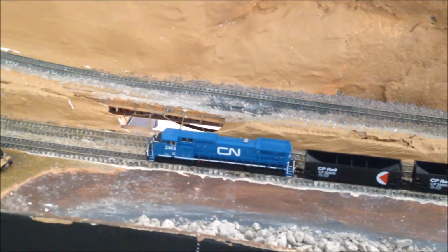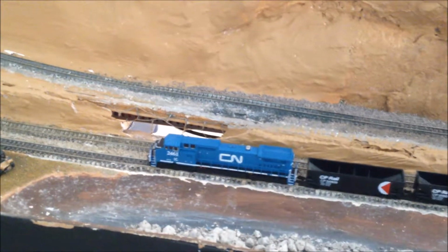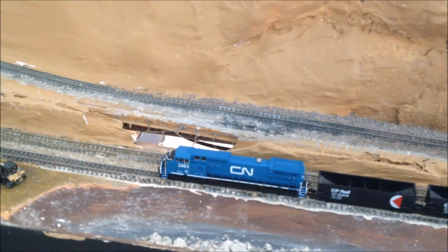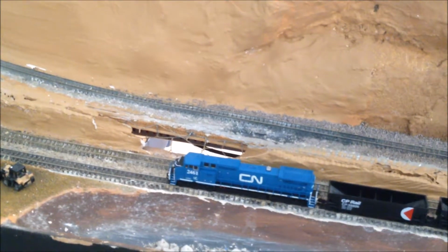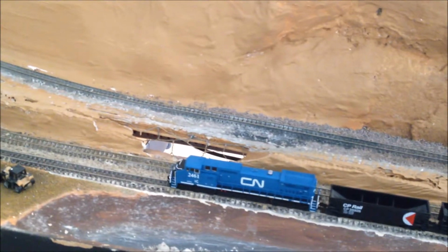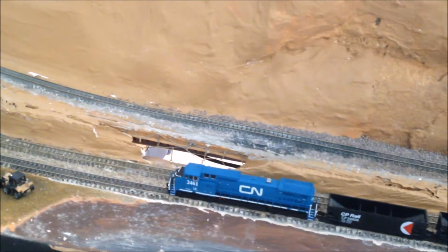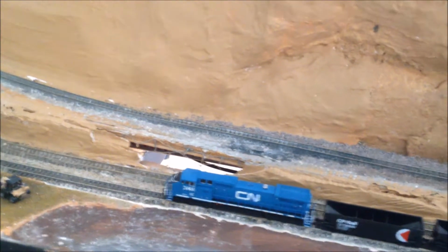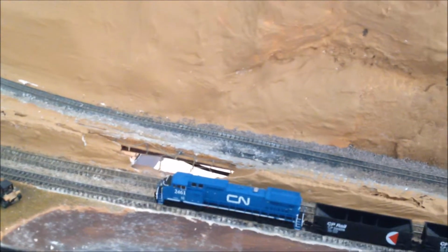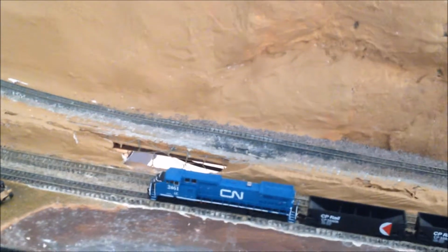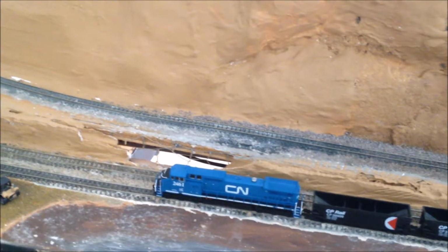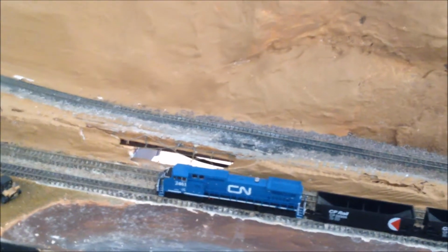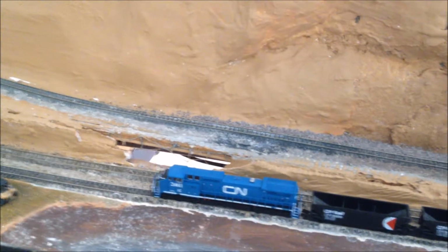What that does is the command station sends your DCC signal, but then there's a little break in the signal where it waits for a reply from the decoder. If it gets some information, it sends that to the command station, and then it continues with the DCC. There's a little interruption, but you don't notice it. The issue is that your command station has to support that, it has to be RailCom aware, let's say.